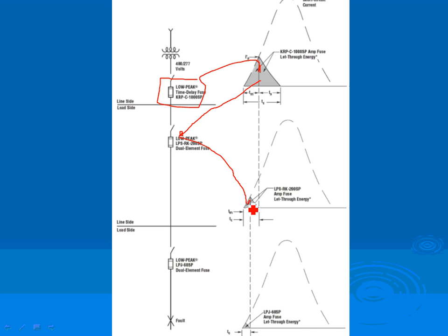Can you see that? This guy is only going to limit it to lower. And the third guy is only going to see this amount going through it, and that guy is going to limit it even more. So long story short, they depend on that limitation of the energy as it goes through the overcapacity devices to get you a tiny little shake and bake happening at the source of the short circuit or the ground fault. That's why they can protect the motors and the contactor and all this good stuff by limiting the current and by opening fast.